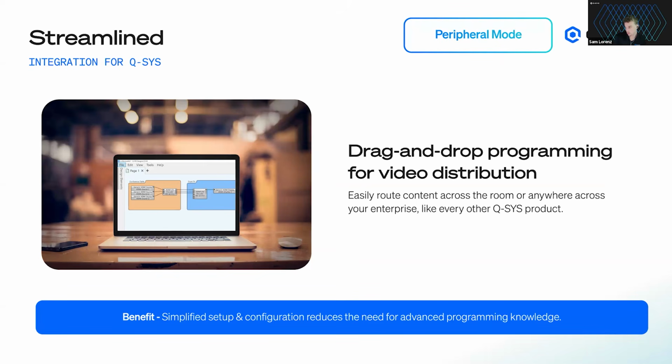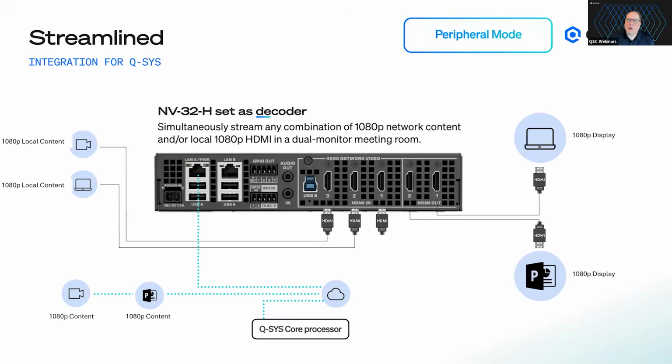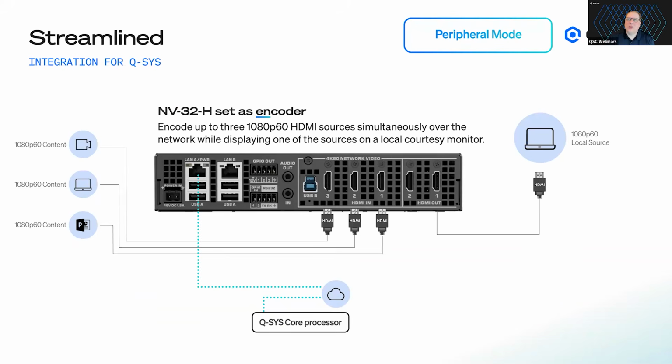Yes, you're absolutely right, Jeff. It's going to follow. You've got an EDID that's being used for all of those encodes. Those encodes are going to be on a 1080p stream if you're encoding three of them simultaneously. So whatever EDID that you're using on the input is going to match the output of that monitor. So if you're using this only as a single 4K stream, then that can be a 4K monitor. But if you're encoding all of them at 1080p, it's going to match the source.